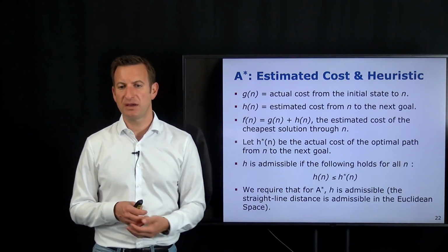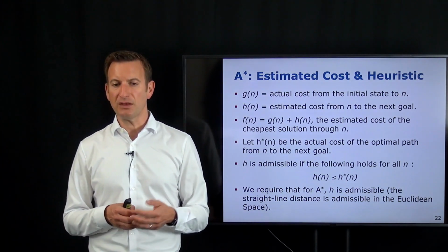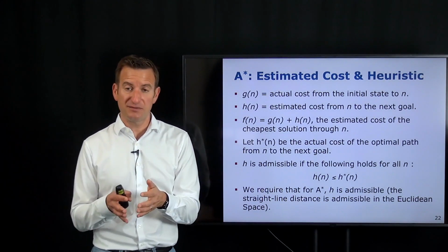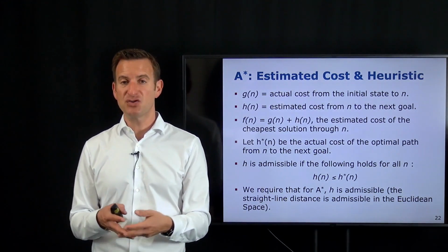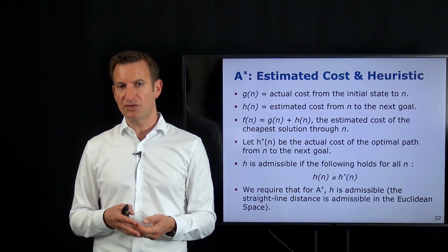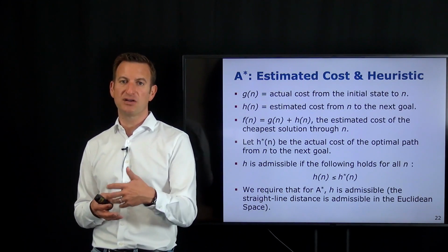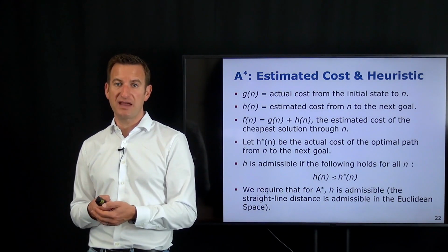So even if you overestimate your heuristic, so assign higher costs than there actually are, your search is faster, you find a suboptimal solution, but in most real-world situations, at least in this Euclidean space where we are working with robots, the path is not, for example, twice as bad as the actual path.